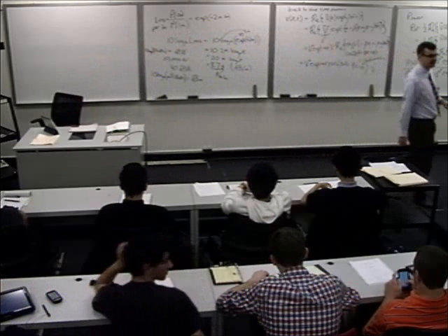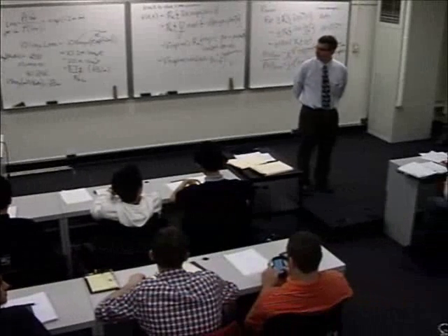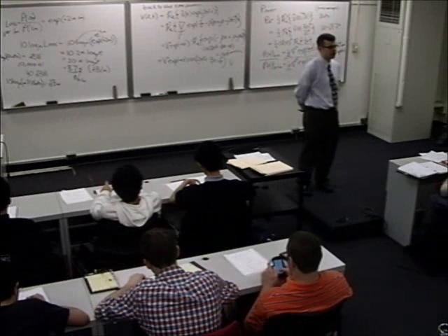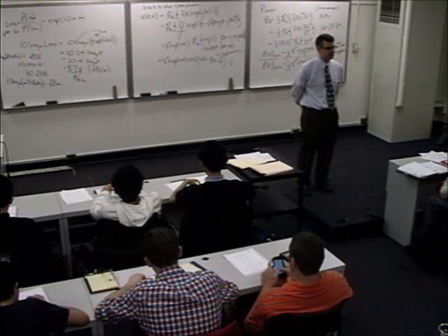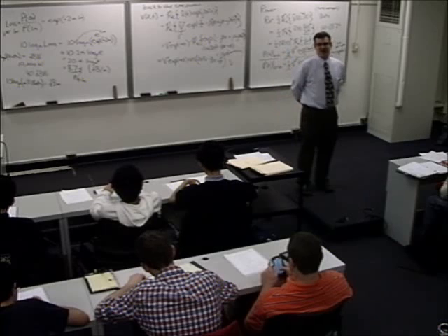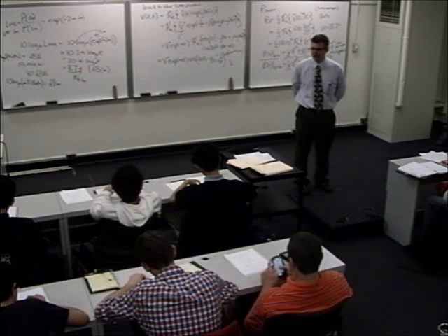What did you say about the 30? What did I say about the 30? Oh, when you're converting from dBW to dBm, you just add 30. Because it's 3 orders of magnitude in the decibel scale larger, 1,000 times larger in the linear scale.